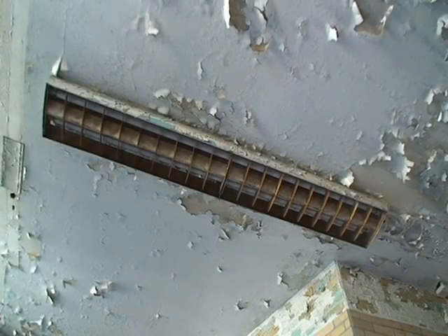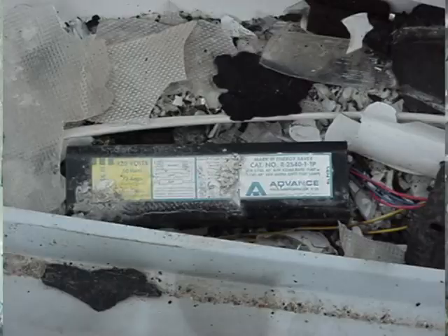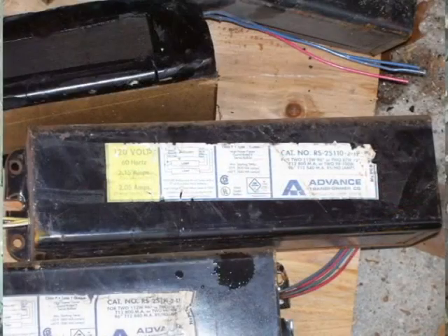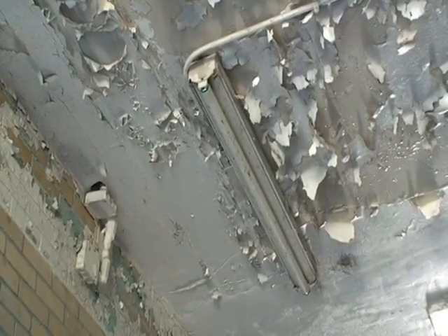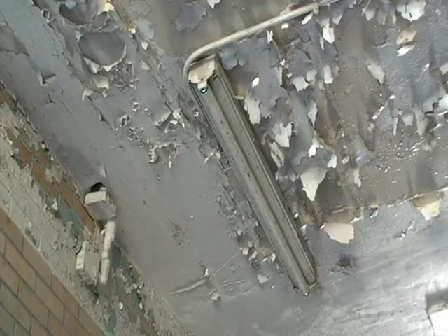This is an older style light fixture. The thing on light fixtures, what you need to be aware of, you can find, or you will find, PCB containing ballast in these fixtures, and then you also need to consider the bulbs themselves because of the mercury content or the mercury vapors inside those. These would both be considered universal waste under RCRA and should be removed prior to demolition and properly handled and disposed of or recycled. And here's just a different style fluorescent fixture, probably a newer light.